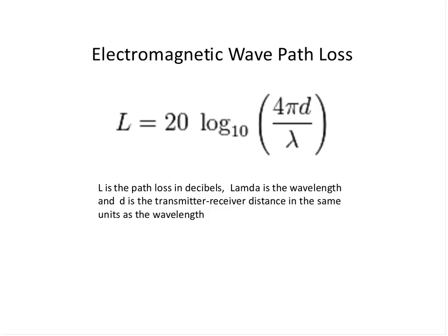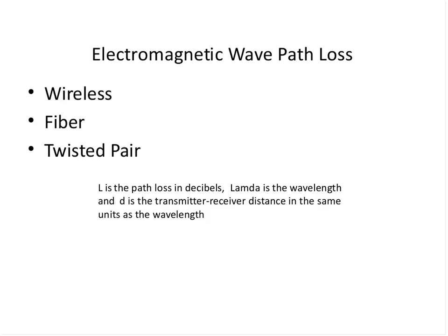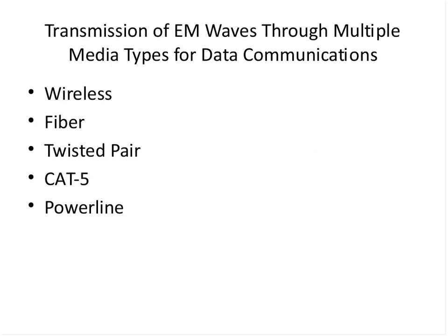Now, the reason why 2.4 gigahertz has become the standard for a lot of home automation is because globally, 900 megahertz is not part of the open public spectrum. It's North America where the 900 megahertz is there. So to have larger market share, vendors decided to standardize on 2.4 gigs for Zigbee and other types of devices. And they were short range. Yes.